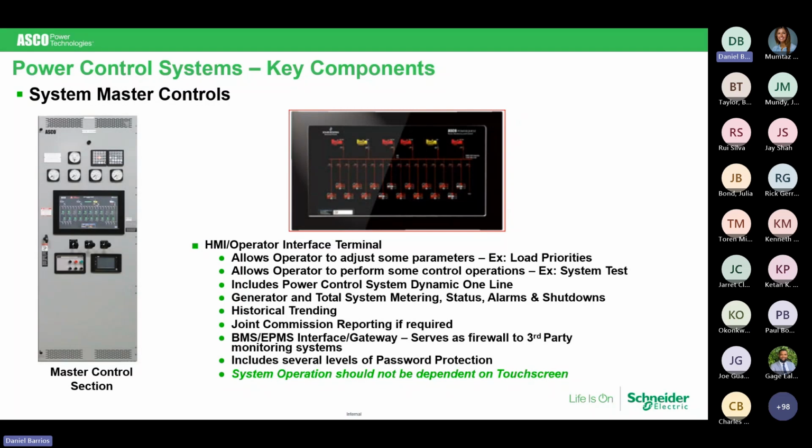That is a capability. There is also in all of our transfer switches a system that we call feature 17. This is what we use in our paralleling switchgear. If you want to do a test online, we are going to close the contact into our feature 17 option. What that is going to do is tell the generators to start and run, and it is going to transfer the load onto emergency even if normal is available and acceptable. When you're finished with your system test, please remember to come off of that, let it go into its cool down timer, and shut the generator down.